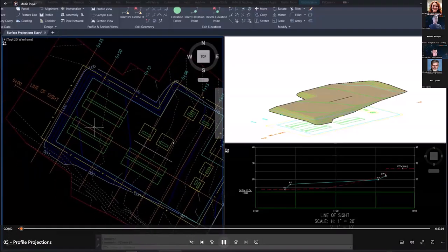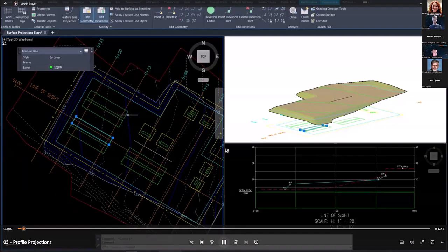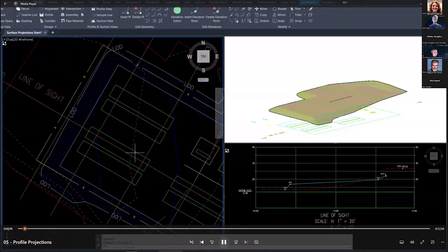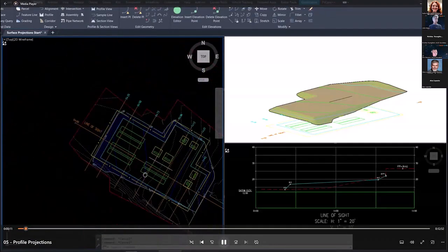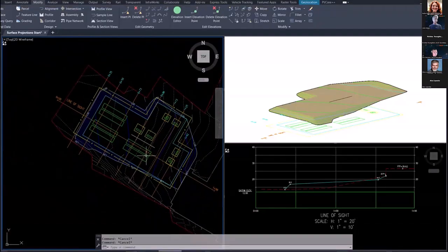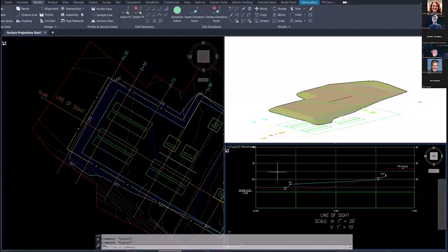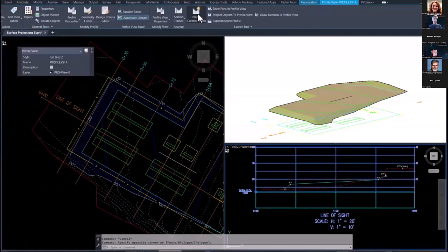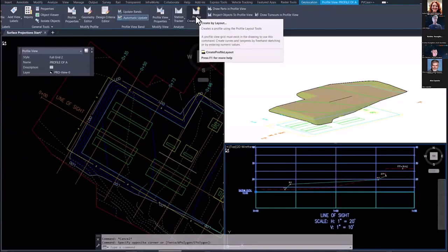All right, we saw how to make simple surfaces out of polylines, and you can use feature lines and many other things, but a lot of their uses that I find practical are really in projections. That's because if we project objects or 3D polylines that are parallel and linear, they work pretty well.